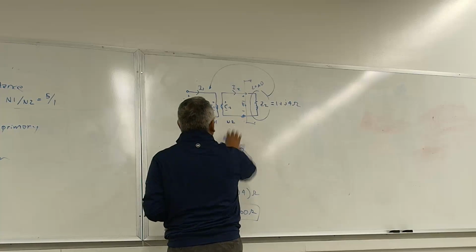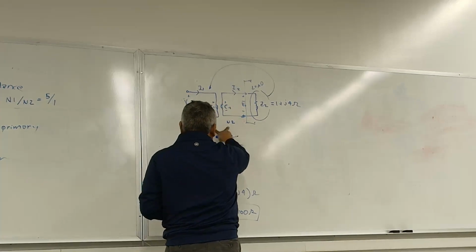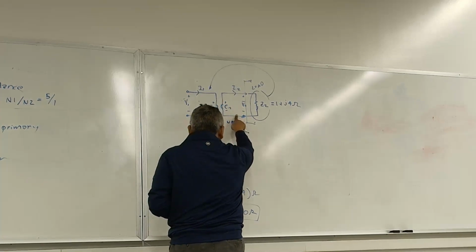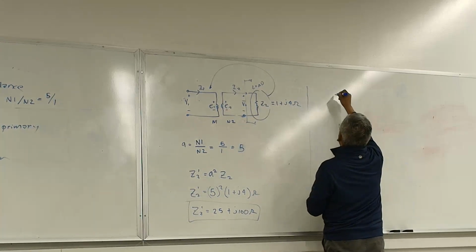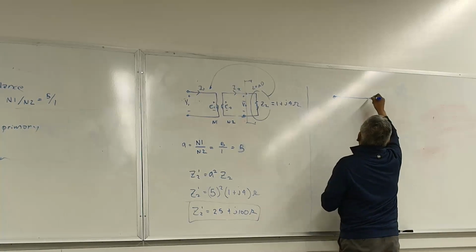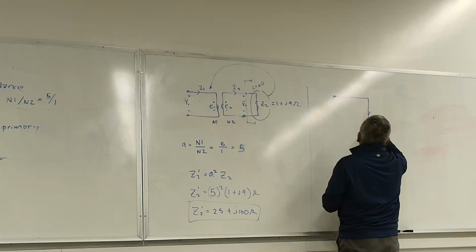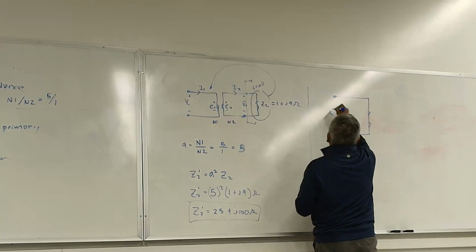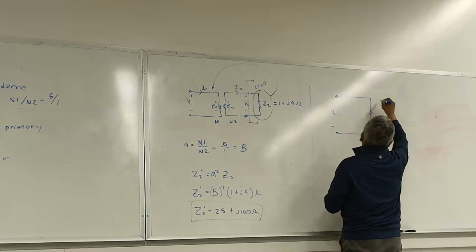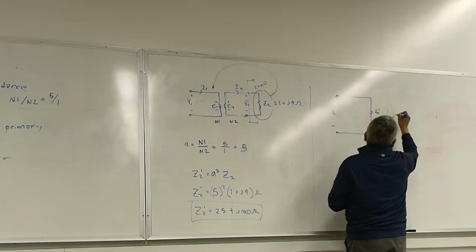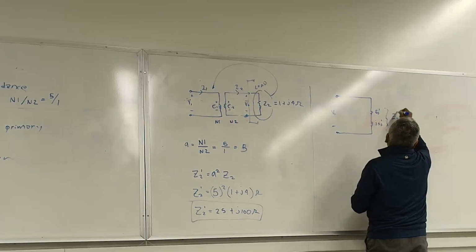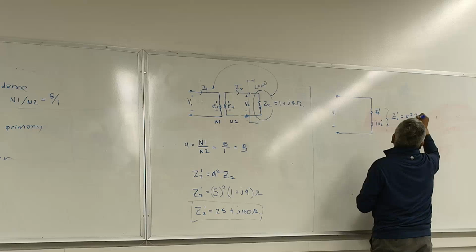Okay, so we can then replace the circuit where we have primary and secondary of this ideal transformer with a simpler circuit as seen from the primary side, which basically looks like this. This is the V1 plus minus, and this is then R2 prime, JX2 prime, and this total is Z2 prime, which is equal to, once again, A squared times Z2.